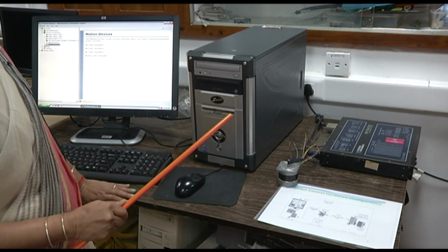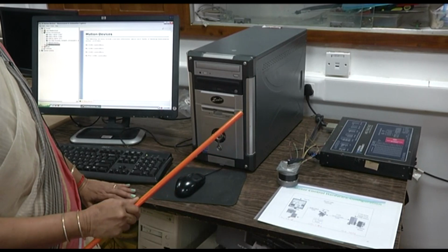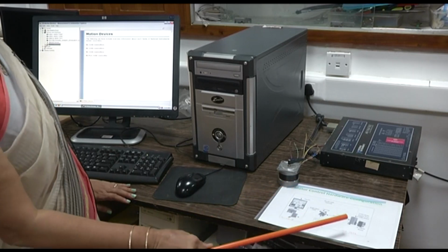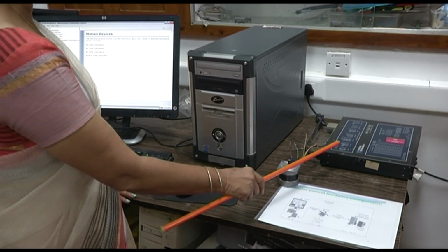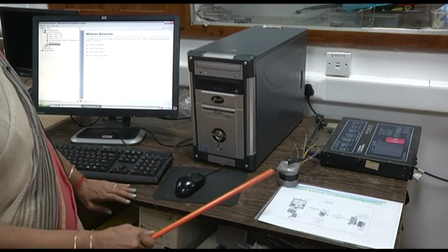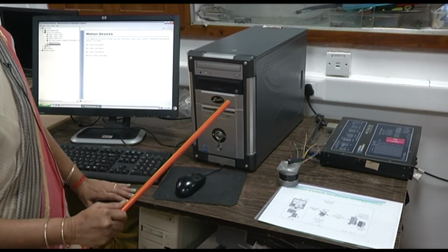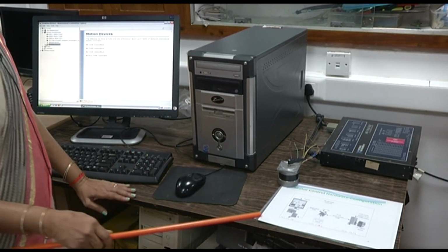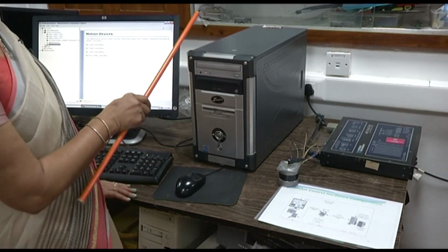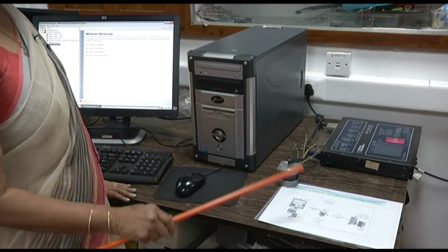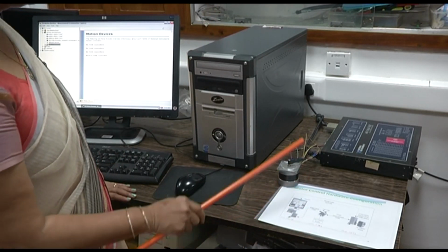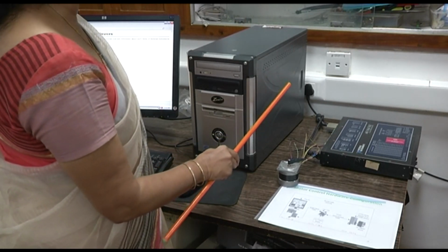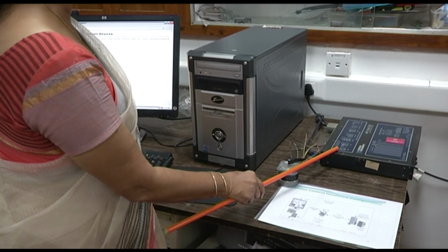Herein, using special hardware like motion control hardware and specially designed stepper motor drives, we can achieve a full-fledged system containing 6 to 8 motors. So, we are using a 7358 controller which is sitting inside this computer. Then we have an interface board, again inside the computer, and this is the driver board, 7604.